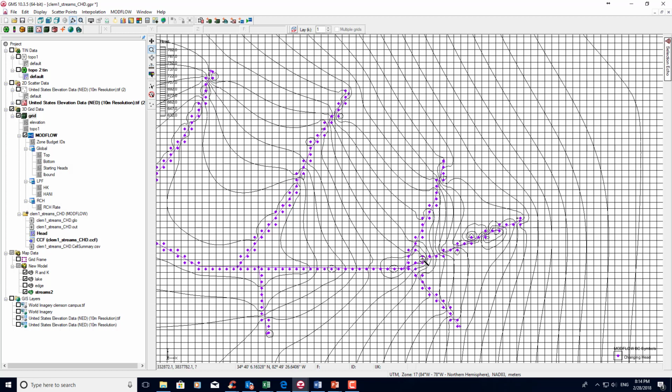Up here, remember we had a problem where it went off to the side of the stream valley, so that's causing some irregularities. Another thing could be that when we have closed contours and we see how this contour V's downstream, this is the signature for a losing stream, and it's a signature for the head up here at the headwaters being too high. And so we would likely need to make an adjustment here.